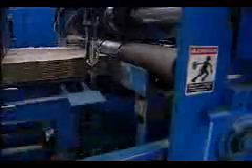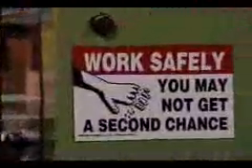Moving parts are a common hazard found when working with machines and are classified as either motions or actions. Motions, such as rotating, reciprocating, and transversing, become hazardous when clothing, jewelry, or skin contacts moving parts. Conveyor belts, gears, and couplings are all examples of machine parts with hazardous motions. Actions occur at the point of operation and usually involve one of the three types of motions described earlier. Actions include cutting, punching, shearing, and bending. A large portion of the machines found in the working environment use some type of action.